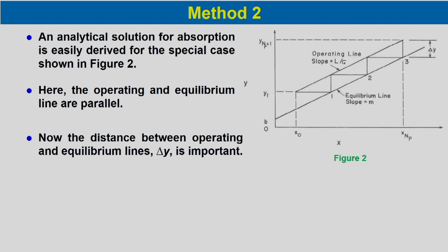Now, the distance between the operating and the equilibrium lines, that is delta y, is also important. The driving force for the mass transfer over here is delta y, and that is constant over here, since they are parallel lines.